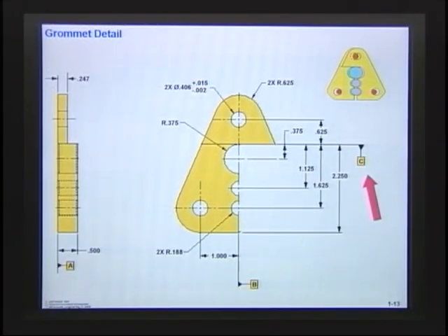All right, the next step that I had to do was qualify the datum features. Remember, that was the second part. Qualifying the datum features, this back face, that's where it mounted up to the bulkhead. I put a flatness on this face, a flatness within 5. Now, why a flatness within 5? If you remember, the requirement on the bulkhead is we couldn't have a gap here any more than 10 thousandths. On the bulkhead I had a flatness within 5, and on this one I had a flatness within 5. At worst case, that could give me a gap within 10. That's where that flatness came from.